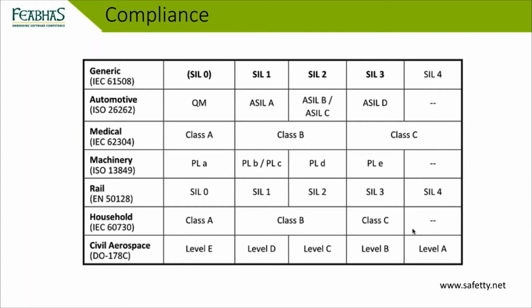Now, again, most of these are system standards and have a subpart with them to do with software. So sort of the grandfather of all these standards, granddaddy of all these standards, is the 61508, where we talk about safety integrity levels, and those different safety integrity levels come about to do with risk assessment. And the different SIL levels will recommend different techniques to be used when developing the system, and especially certain aspects of the software.